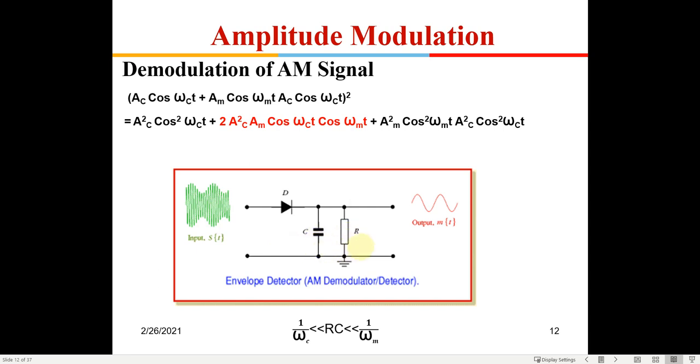So that is a filter. This is basically an RC low pass filter. Okay, for high frequencies, you know the impedance of a capacitance is 1 by C omega, right. So for high frequencies it will be low impedance, so the output will get shorted here, it will not get reflected here, right. For low frequencies, this 1 by C omega has omega in the denominator, and omega is very small, so it will not get shorted out. So you are putting a high impedance, so that the output will be available. So this is how it works.